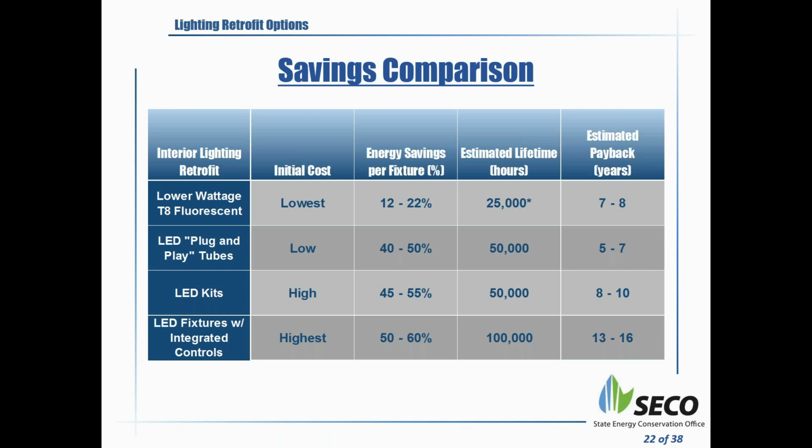Now, why are the payback ranges different? I think that's one of the questions somebody posed. The paybacks are different because it depends on the operating hours and the cost of installation. Those are the two things you have to watch out for. Somewhere with lower operating hours, you will have a longer payback for the same cost as somewhere else with longer operating hours, which will have a shorter payback. That's why you see a range of these paybacks, and that's why it's good to do an initial assessment to make sure you're looking at the payback ranges and the application hours of operation and so on.